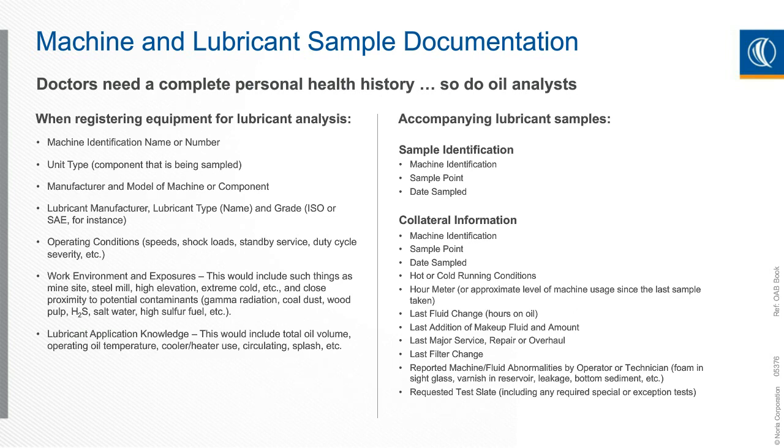Is it a hydraulic oil? What type of viscosity is it? What are the operating conditions? Is this something that's seeing a lot of starts and stops and shock loads? Is there high temperatures typically, or is it in a cold environment? What is it typically seeing? What is the overall work environment? What things could it be exposed to?